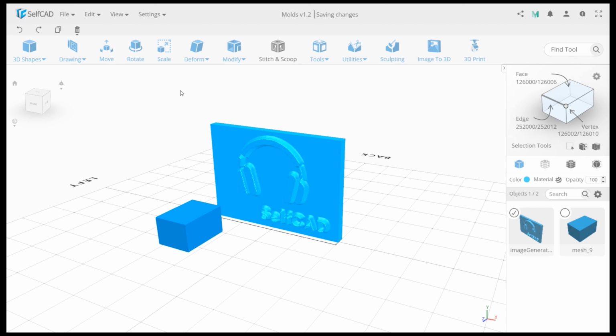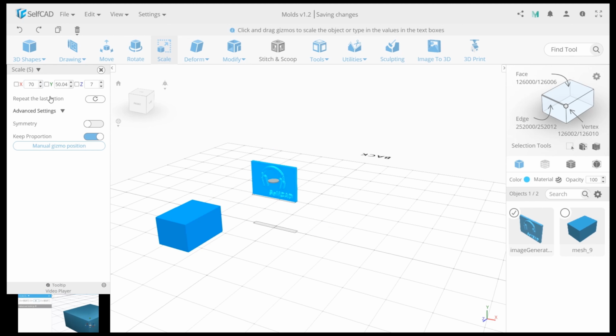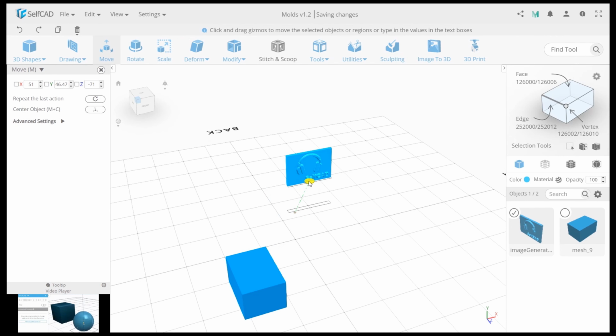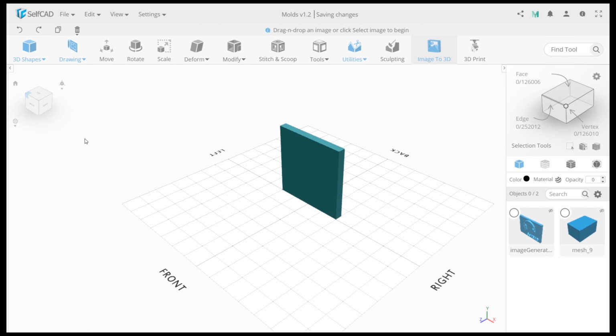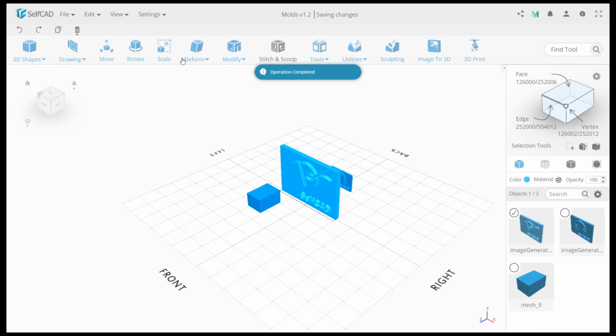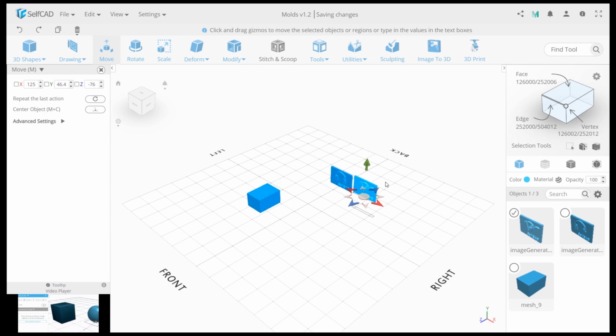Now that we have the first 3D image ready, we will scale it to fit our object's length of 70, while proportionately rescaling the other two sides as well. We are doing so by using the Keep Proportion option, and we set the x-axis to 70. Our soap mold design requires 4 different patterns, so to work in an order, we will first create the remaining 3 shapes before moving on to the next step.